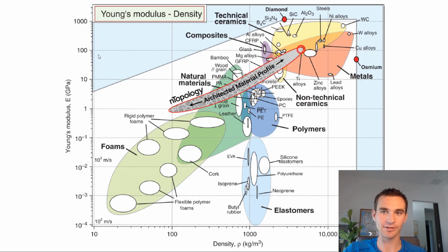So we see people taking titanium, for example, which they can print confidently, and they want to modulate the material properties to, say, behave like bone if it's going into a medical implant, or improve the thermal conductivity of titanium by increasing the surface area or what have you. So homogenization is a way of quickly predicting how much these changes will have an influence.